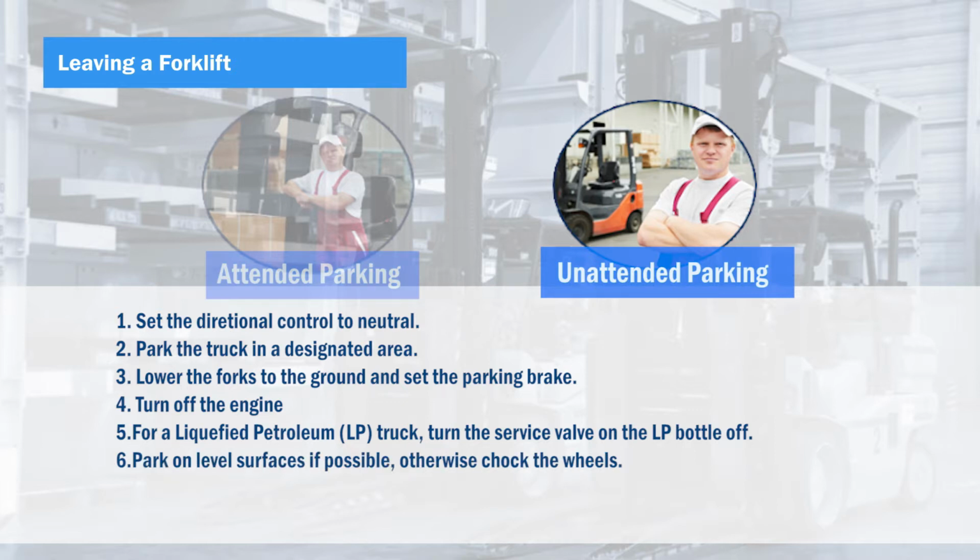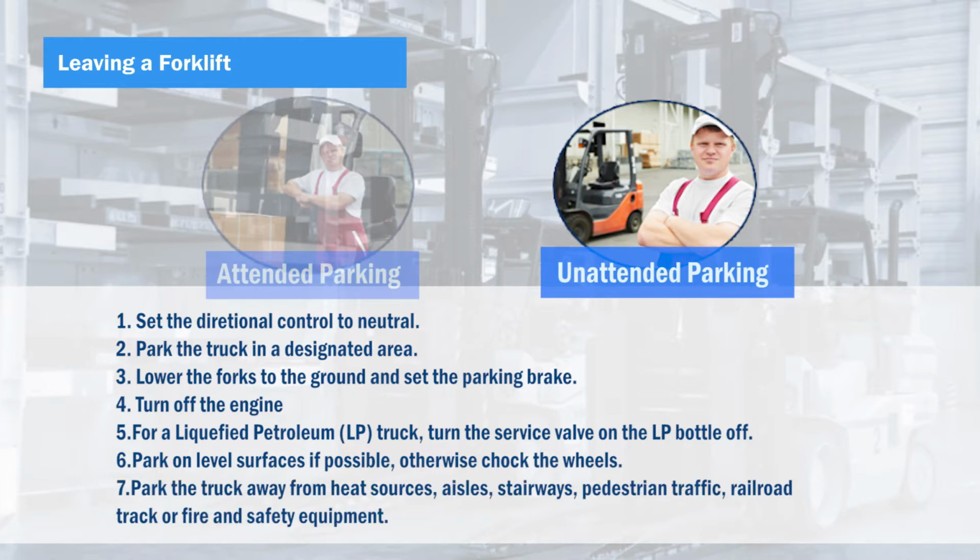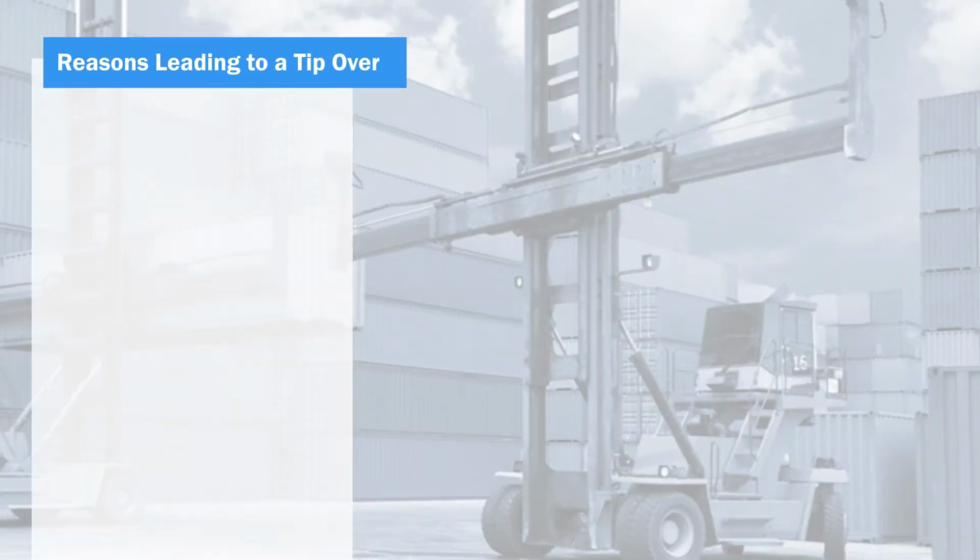Park on level surfaces if possible, otherwise chock the wheels. Park the truck away from heat sources, aisles, stairways, pedestrian traffic, railroad tracks, or fire and safety equipment. Reasons leading to a tip-over.